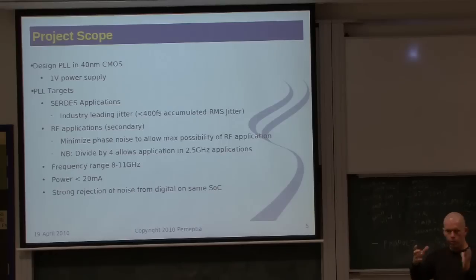Now, phase lock loop, we use an oscillator, which can be running at 3 gigahertz. We can divide its clock down by 100 to the 25 megahertz level, and then we compare the phase. So we can check the timing between the edge of the reference clock and the edge of the divided clock and line them up. When every edge lines up, then we know the divided output of our oscillator is running at the same frequency as our clock, and hence our oscillator must be running at the divider times faster.